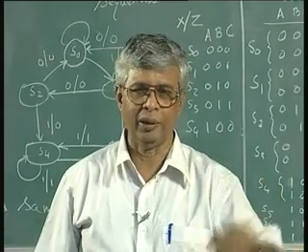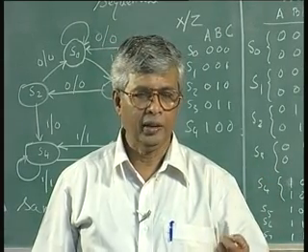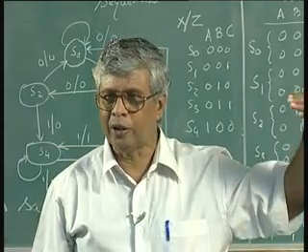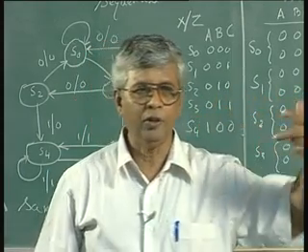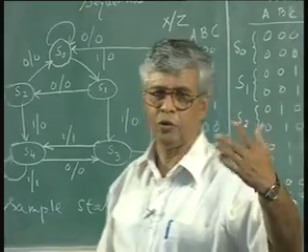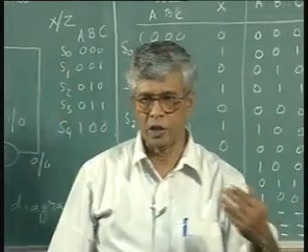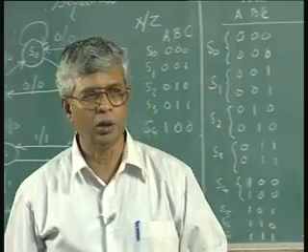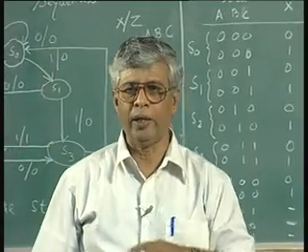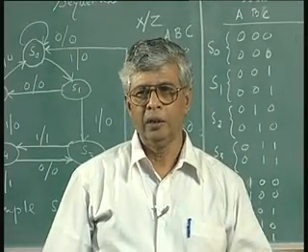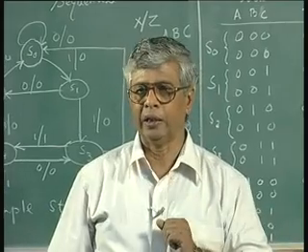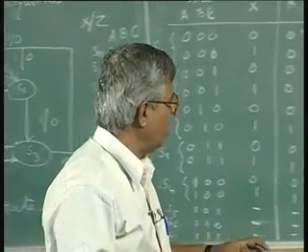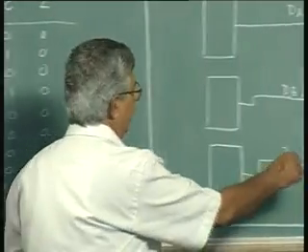So, the multiplexer is a selector mechanism. I can have the select signals as the present state and the corresponding input will be connected to the output. Suppose you have a 4 to 1 mux, you have 2 selectors and 4 inputs. So, when the selectors are 0 0, the first input will be connected to the output, when the selectors are 0 1, the second one will be connected, and for 1 1, the last one will be connected. We will use the same argument here and give the values of the present state, the ABC which is available here.